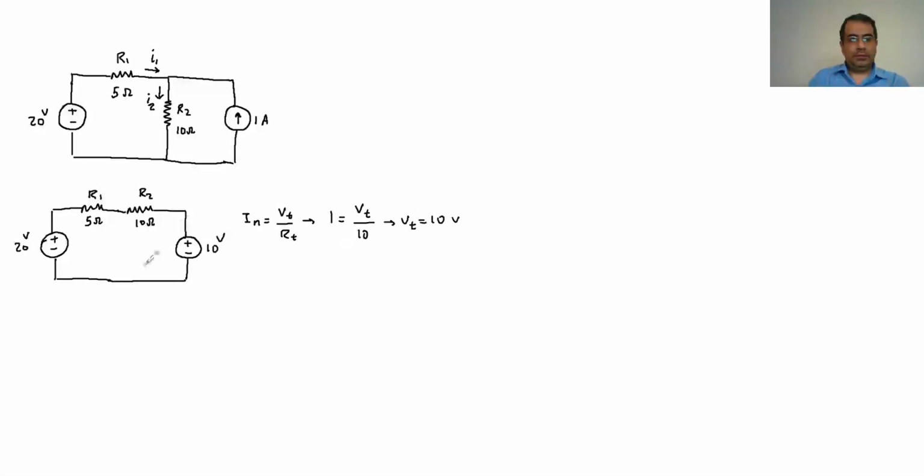So now I have this circuit, and look at the I is going there. So the I is going to be that I1 because it's the I1 going in that circuit. Now that I have the voltage, look at the circuit. It's a very simple circuit. You have 2 battery, 2 resistance, and you want to find the I1. So the next step is that I will go ahead and write the KVL in this circuit. So it tells me the sigma V is 0.